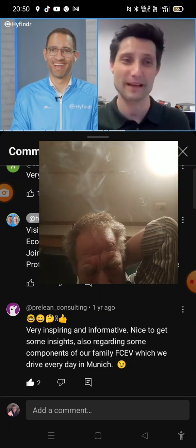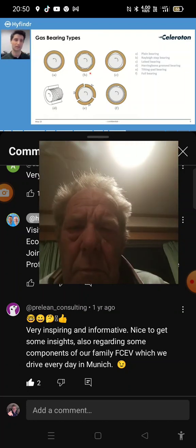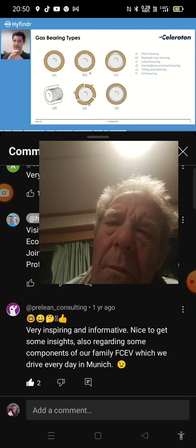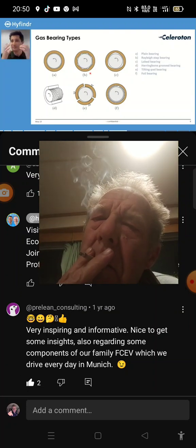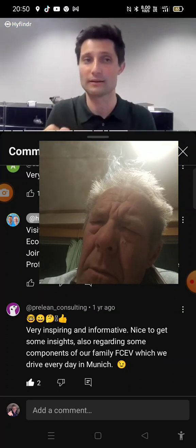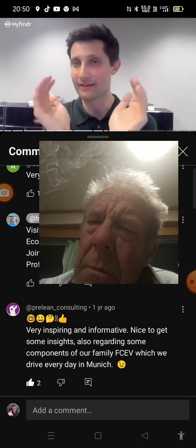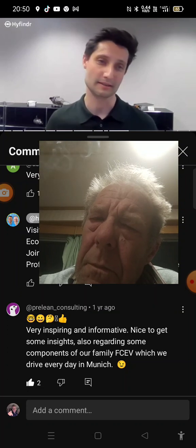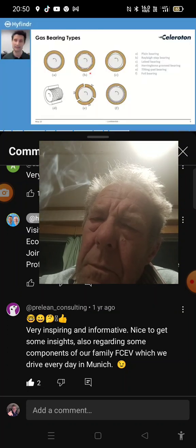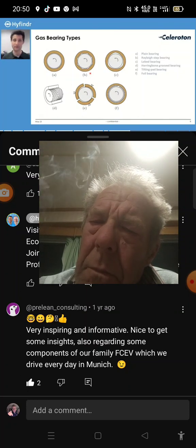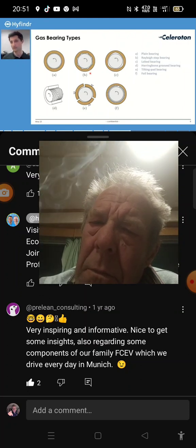I can maybe briefly show you. There are different types of gas bearings one could use. The simplest one one can think of is a plain bearing, where essentially it just has a cylinder and a bushing, which is a pipe, so to speak. And just by rotation and the Couette flow, one generates a cushion where the rotor starts floating. It has a narrow regime where one can operate these bearings. And for instance, the technology that we mostly use is herringbone grooved bearings, where we can engrave structures to increase the regime where these systems can operate.